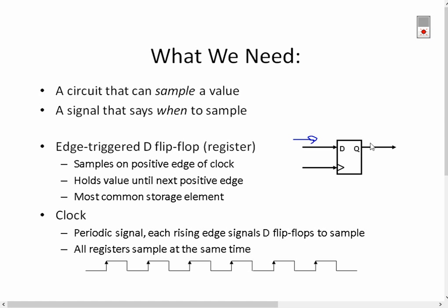We have our output, which is our ability to read that data, what's coming out, and then over here I've essentially got my switch. And this switch in this simple circuit essentially says, when I turn this on, it allows me to load a new value, and when I turn it off, I cannot load a value. And this switch down here, this control, which normally I'm going to attach to the clock, right? This is how I have the opportunity to actually change the value. Okay?